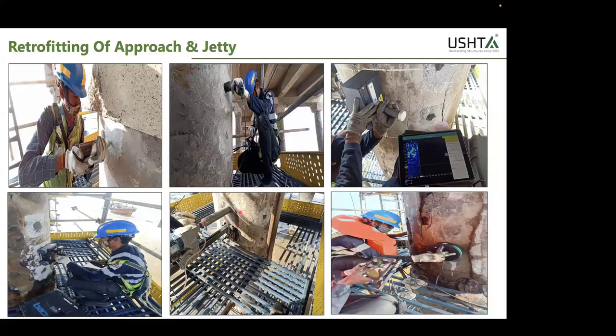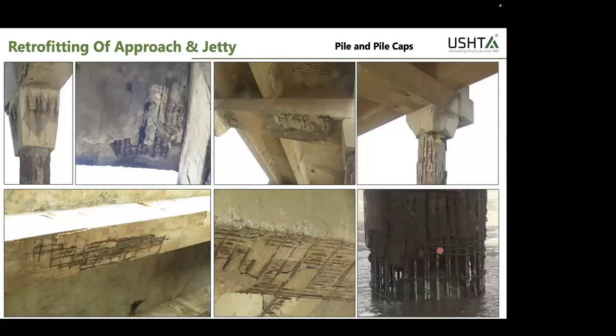Then this is the core test, so we know the exact strength of concrete. And this is for corrosion. We are doing the I-core, which will give you the potential and the corrosion rate, and all those in graphical representation. So after we did our audit, we came to a position that we knew exactly what went wrong. And see, these were the photographs of the repaired portion.